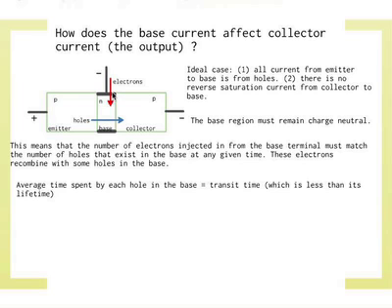So another way to think about this is, why do the electrons come in? If there is no recombination here, there is no need for electrons coming in. The holes come in, they just leave. So if I were to just draw the base region, I have holes coming in, this is IEP, and holes leaving here. I'll call it ICP, collector current. And base electrons. If these two are equal, I don't need that. That would be 0.